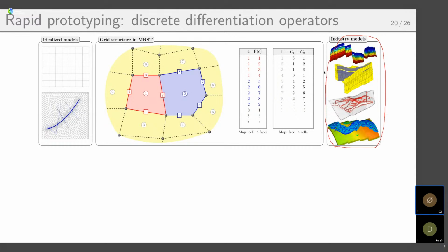And these can, for instance, be in the so-called corner point format, where you have all sorts of strange topologies. A cell can have any number of neighbors, not just, for instance, 6 that you would have in a logical Cartesian grid in 3D. I've actually encountered corner point grids where you have 26 topological neighbors. And we would like a fully unstructured grid format that's able to deal with everything ranging from simple Cartesian and all the way to these complex corner point formats, and of course, including Voronoi type diagrams.